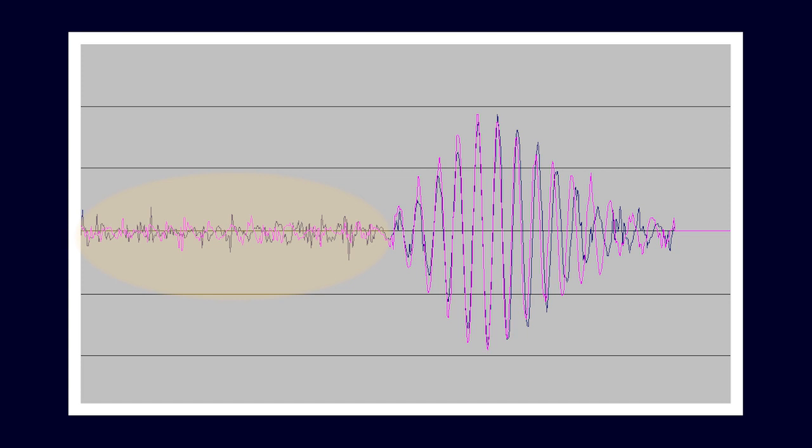A situation where you might want to try lowering the received signal averaging is if the flows are surging forward, either for pulsating flow. Typically this is what you would see in gas and not liquid. And when the meter has a hard time latching onto the signal, sometimes a lower signal averaging will allow the meter to respond more quickly.